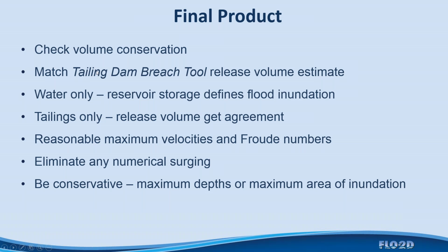If you use the tailings dam breach tool, and you're not going to model the actual tailings dam breach itself, and you just want to impose the inflow hydrograph on your downstream reaches of your dam, then that's fine. If you're going to breach it in the model, like I just showed you in the example, then the tailings dam breach tool will give you that estimate, and you want to match that estimate with the volume I showed you in that summary.out file.